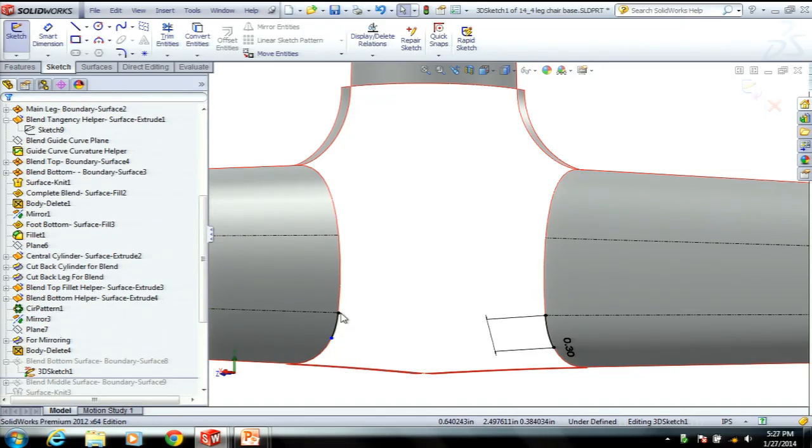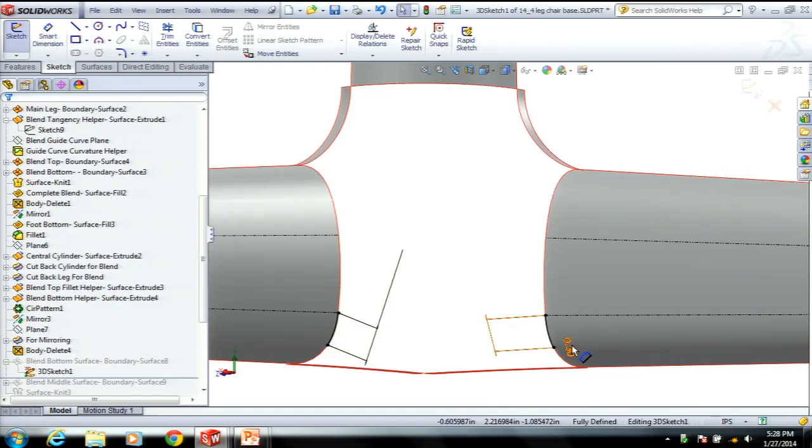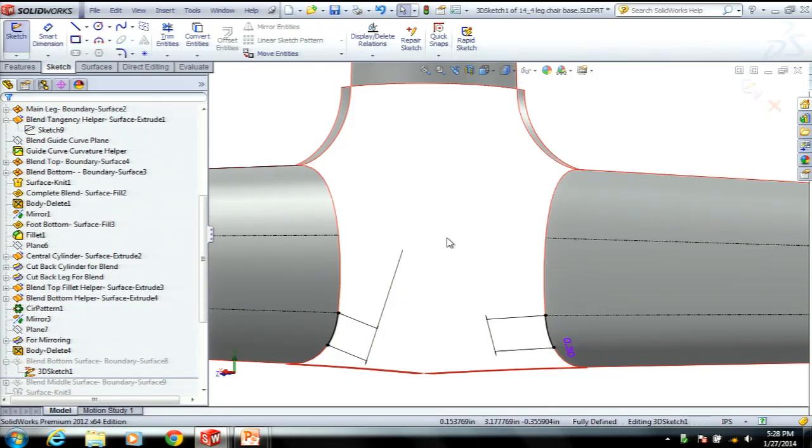And then SolidWorks 2014 added an equal spline relation. Unfortunately, it doesn't work on these converted edges. It gives you a warning about fixed shape splines. And then I just added a dimension. And I should have been good, but I was a little lazy. I should have right-clicked these dimensions and unchecked Mark for Drawing. That way, if your detailer uses model items, these dimensions that were only used to help define our surfaces aren't brought into the drawing.